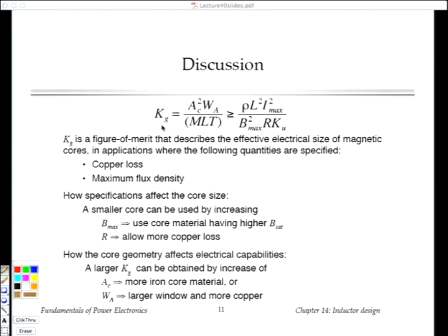Kg varies inversely with resistance. If you don't care how big the resistance of the wire is, you can make R big and you can make kg small. And everything else maybe will be the same. So if you don't mind having a mega ohm of winding resistance, you can put 1,000,000 in there and get a teeny kg, smallest core on the list, and get all the inductance and all the current you want, but you just have all kinds of loss in its resistance.